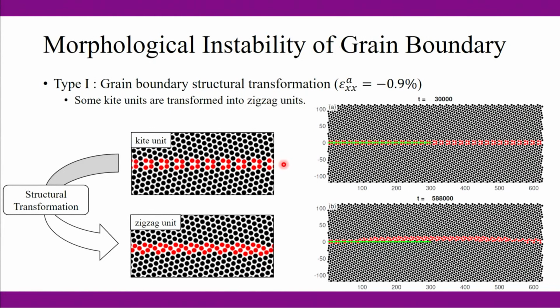But once the compressive strain is too large, and maybe the dislocation cores they feel are too close to each other, now the interface is trying to move the whole line, homogeneously, to some other place. By doing so, you are expecting to see a configurational change of the whole planar surface, and that will lower the energy. That's associated with this idea of coincident site plane.